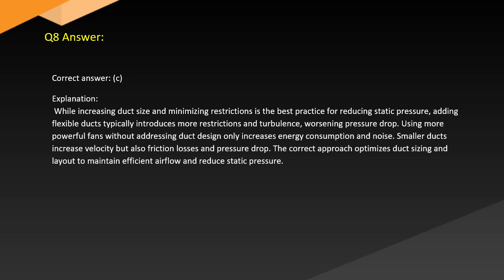Using more powerful fans without addressing duct design only increases energy consumption and noise. Smaller ducts increase velocity but also friction losses and pressure drop. The correct approach optimizes duct sizing and layout to maintain efficient airflow and reduce static pressure.